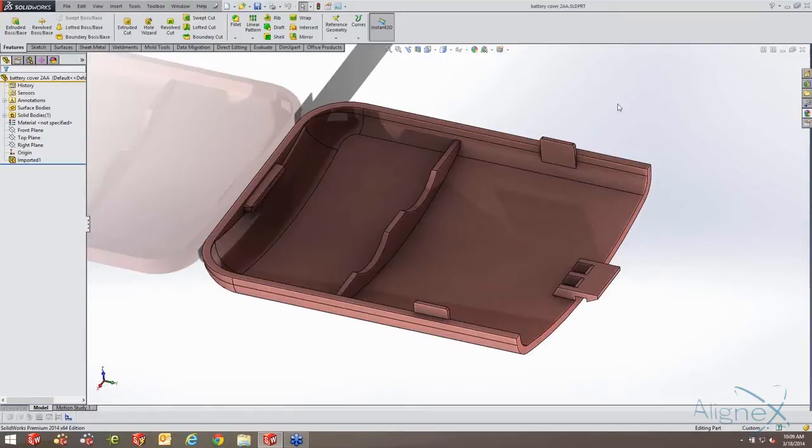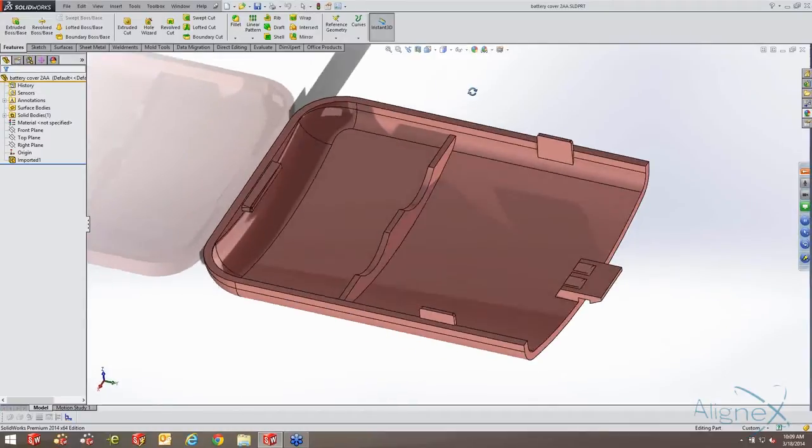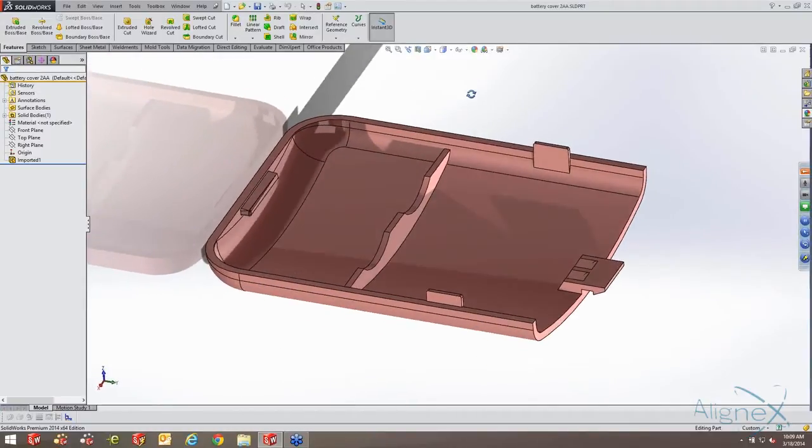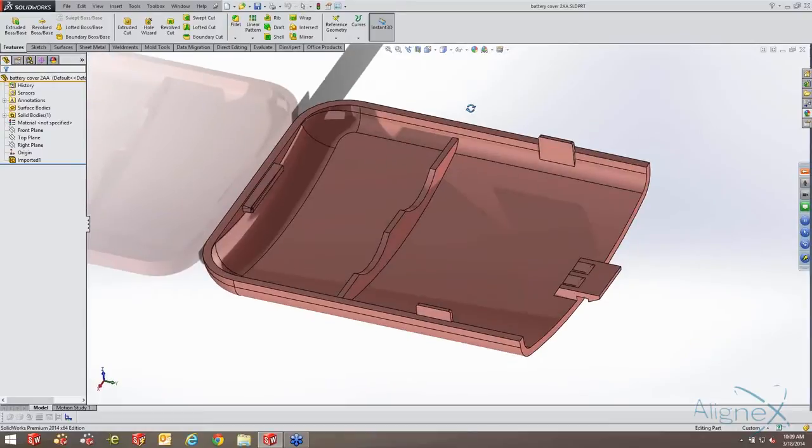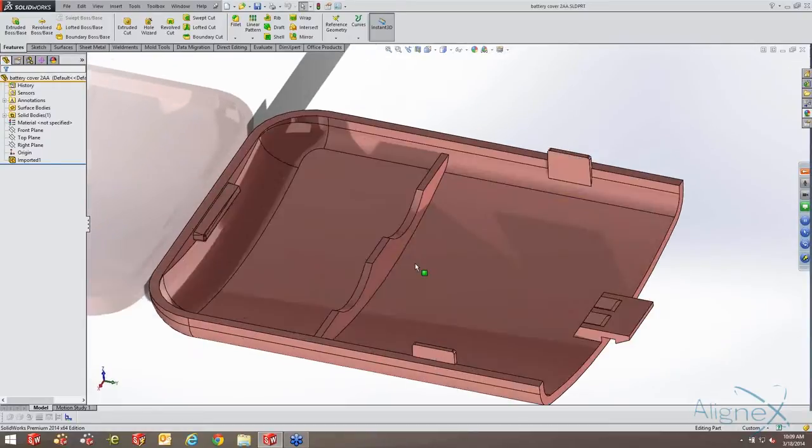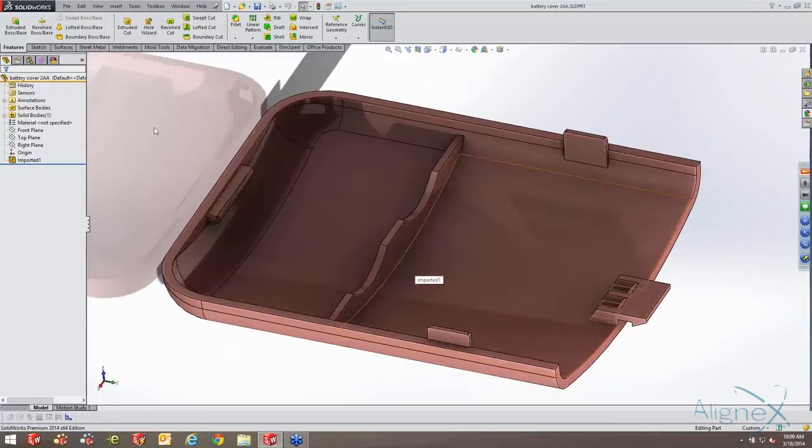Everyone, I am going to be showing you SOLIDWORKS Plastics. And like Dean had mentioned, we're going to look at the fill pack and then a sample of the warp cool module. There are three modules that Plastics comes in: the Pro, Premium, and Advanced. The Pro is your fill module. The Premium has fill and pack. And then the Advanced has the fill pack and then warp and cool added to it.